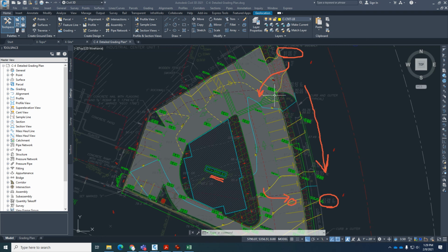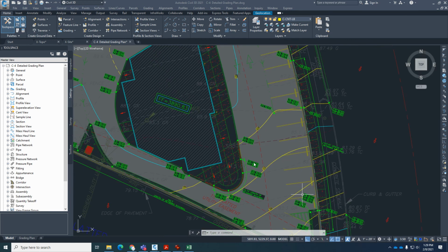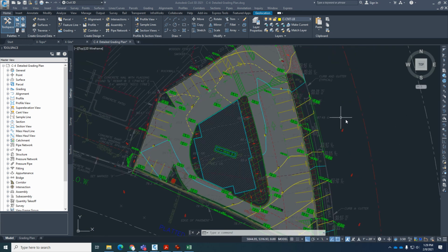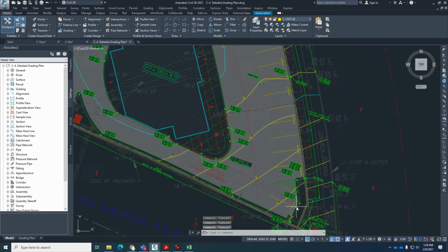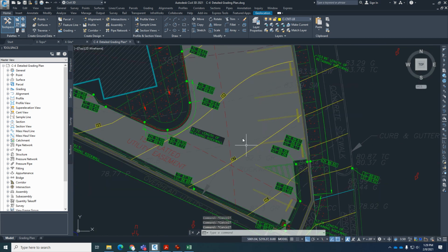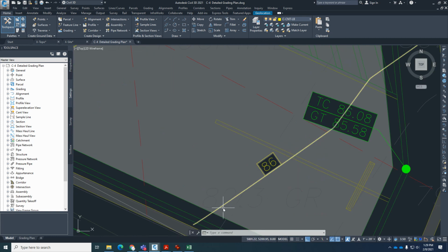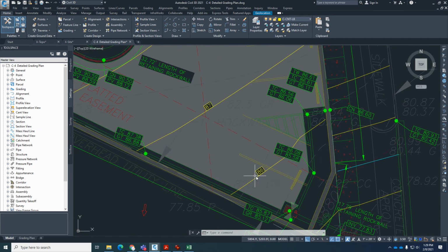Okay. And that's the purpose of the civil, and what we're doing is we want it to be comfortable, meaning you park your car, you're able to get off nicely and walk up to the building and do whatever you're going to do at that building. Okay. So that's good design. And in here, like I said, here we're filling about 4 feet somewhere down here. This is 82. We're up to 86. So yeah, we're filling about another 4 feet or so in this area.